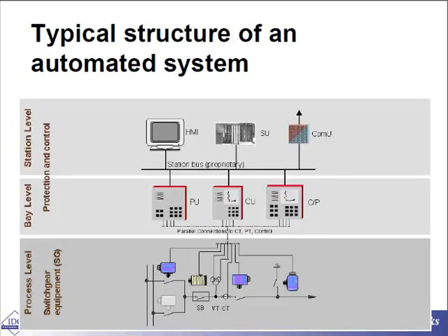Now, in terms of the new concept that led to the development and creation of 61850, what was the goal? One more time, the goal was to simplify the system automation. The goal was to reduce as much as possible the wirings, cablings and connections, marshalling boxes, termination boxes, things like that, just to save time, to save money, and to simplify things. So basically, these days you are doing that in your daily life.